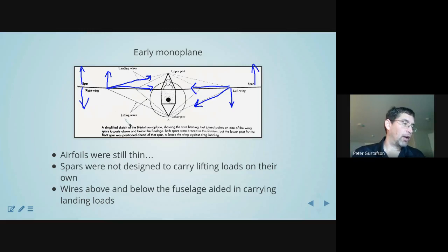Caden says no flexibility. Josh says the structure in the fuselage will have a lot of force on it that it has to withstand. Joel says the fuselage has to support compressive forces coming in from the spar. Those last two statements are true. Obviously, there is going to be a compressive force coming in towards the fuselage. Now, whether that is something the fuselage can handle, actually, it wasn't the fuselage that was limiting.